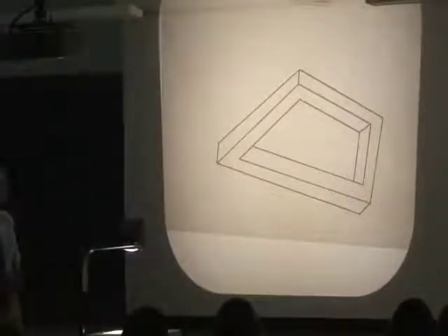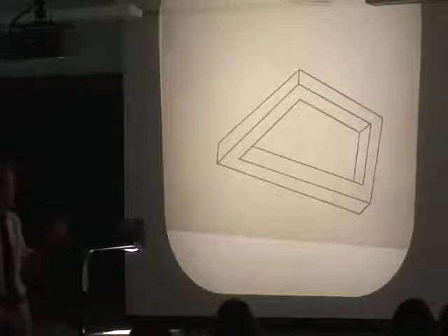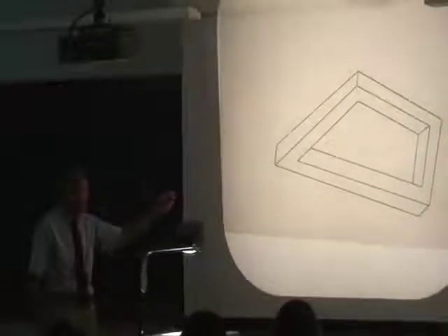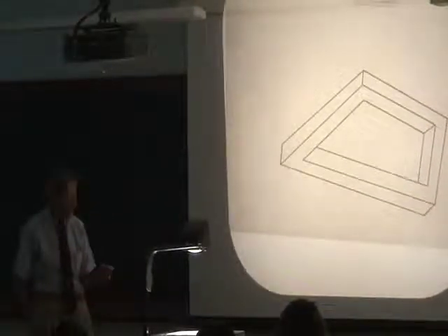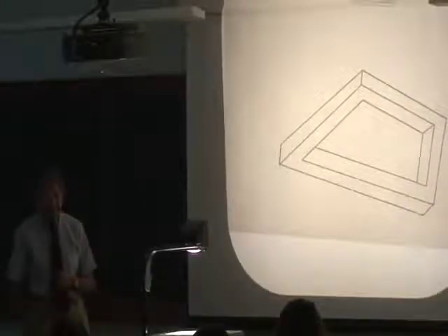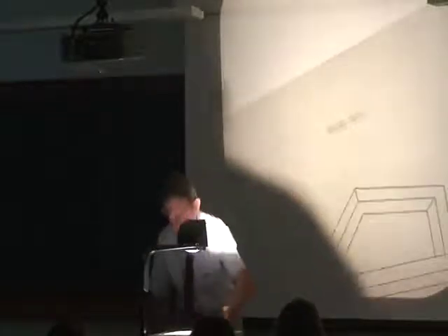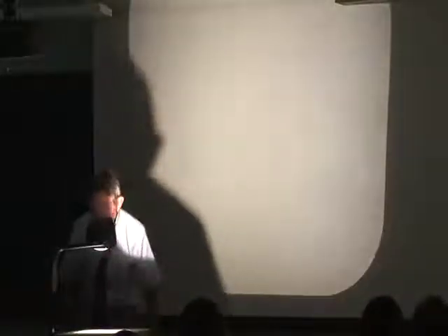Okay. The worst thing you could get, and what did happen sometimes, is that you would get a credible answer. And you wouldn't know that this was not a legitimate solid, and you might try to machine it or something. And then you would have a serious machine tool failure in your shop. So, again, a lot of money down the tube. Modern CAD systems got this fixed about 1980, and now they're quite reliable. Well, that's enough on the mechanics of design representation. Learn to use your CAD and love it. I'll talk just briefly about the process of design.